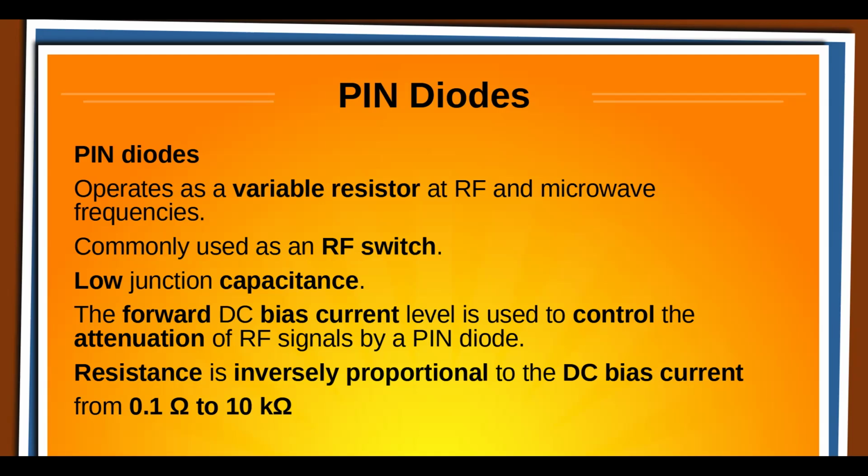These are similar to a MOSFET, using a MOSFET as a switch. Well, I guess you could, but it's a lot simpler to use a diode and bias it. And you can actually get the same effect with something like a 1N4007. That's kind of a typical power diode, handles a few amps. They will act like a cheap pin diode, not as well, but they're a lot cheaper. One of the advantages is very low junction capacitance, where with the MOSFET, you're going to have more capacitance.